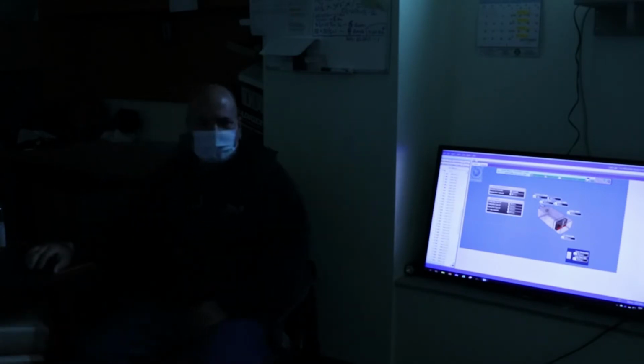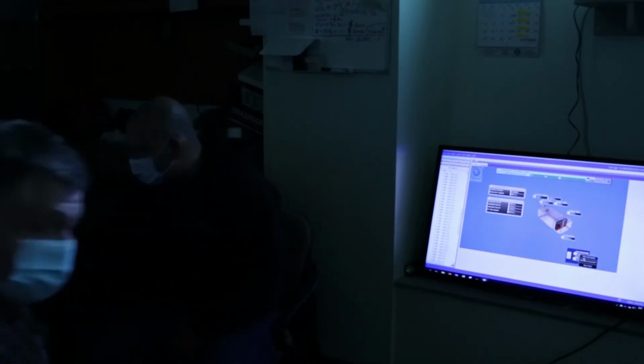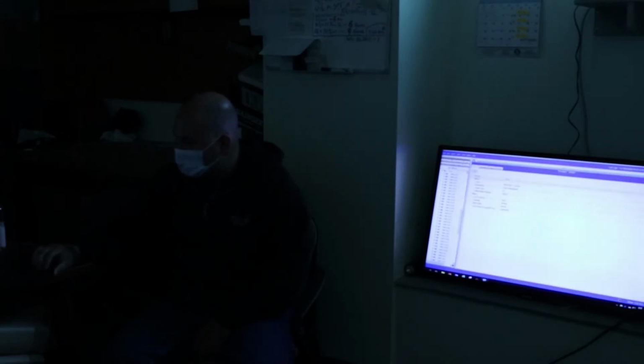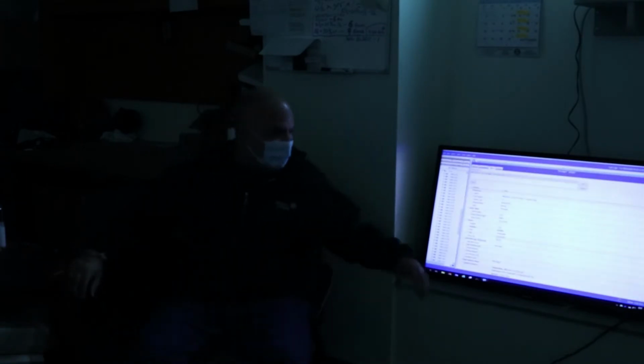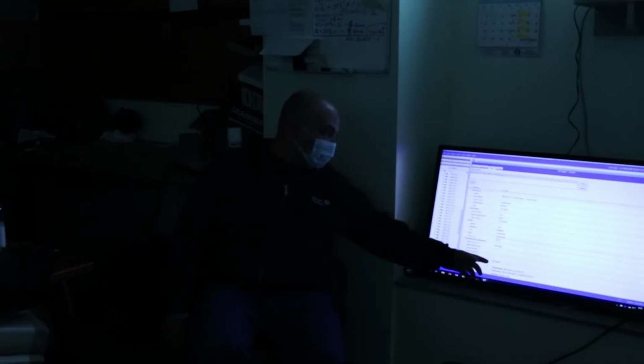You can get to that adjustment by clicking on the point. If you click on the actual point, we can get to the alarm tab like that. You don't have to go to the tree to do an adjustment. So we could change the 80 or the 65.